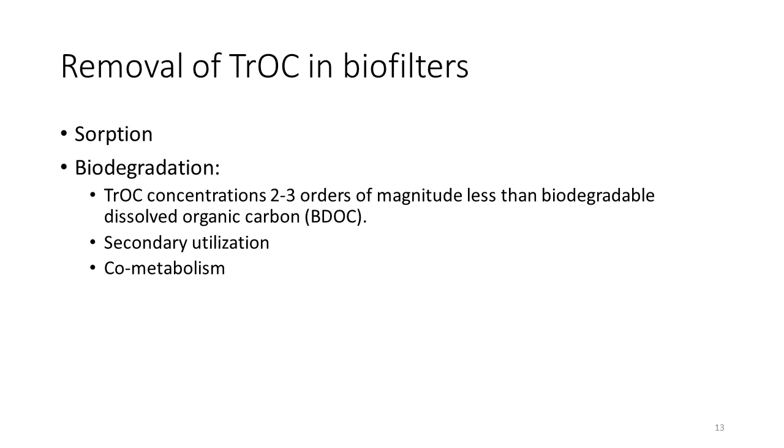In typical biofilters, there are two main mechanisms for removal of trace organics. The first is sorption onto organics, either onto your organic media, onto natural organic matter, onto biomass in the biofilters, or onto any kind of extracellular substances that are produced. The second mechanism is biodegradation.